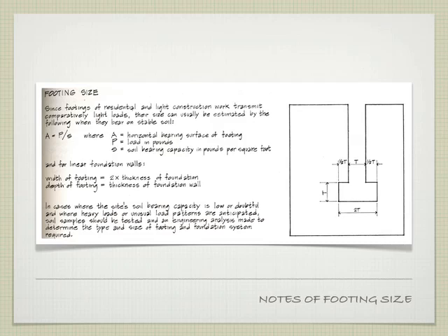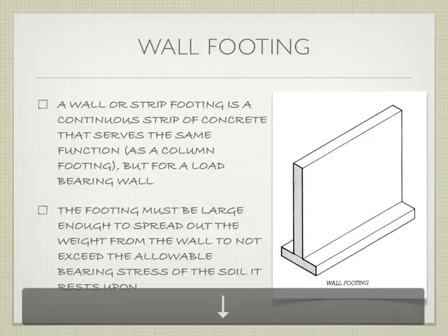Footing size. I'm not going to ask you to calculate how big a footing would be. This is too much information. It's for more of a structural class, which you're, of course, going to take at some point. If you go to Berkeley or Cal Poly, you're going to end up taking one of those classes. But the idea here is that we have a variety of factors that allow us to calculate, based on how concentrated our point load is, how much width we need in our footing based on what the load is and the bearing capacity of the soil. You can look those up later if you want.